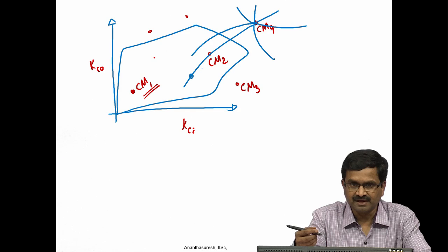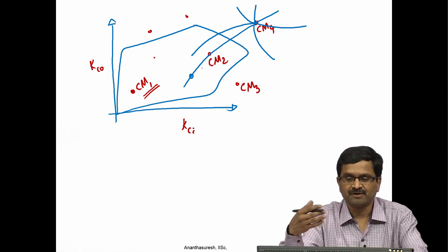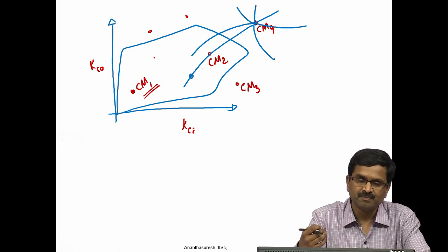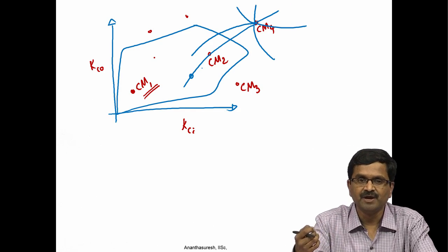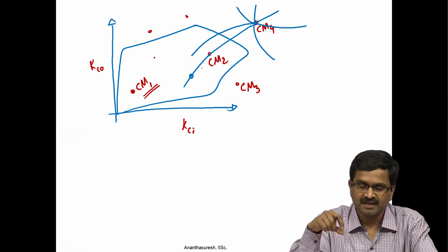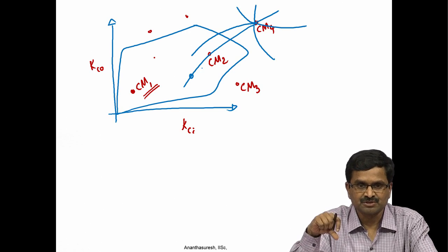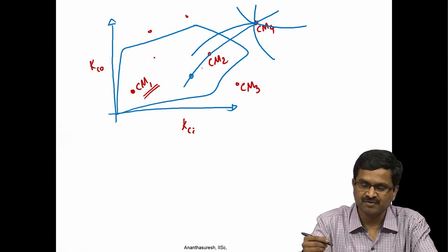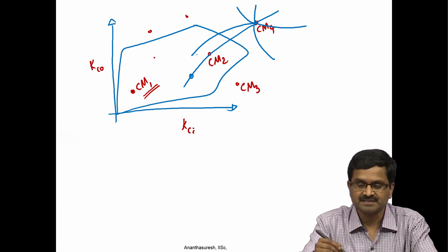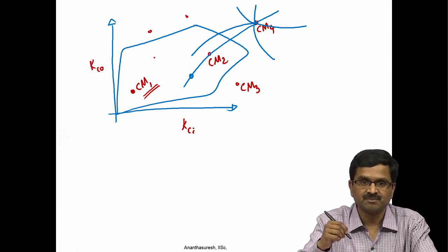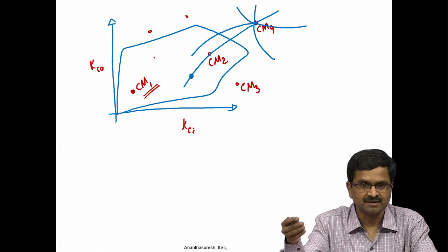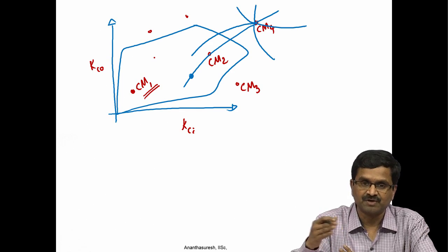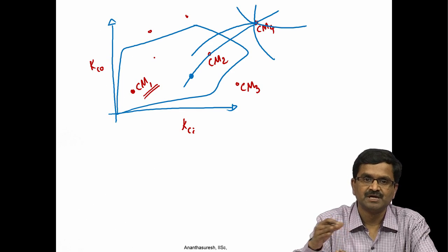While designing that, we can look at the strength as well as manufacturing considerations such as the minimum width of the beam that can be made using a process that you can select. You can select manufacturing processes and then set the manufacturing process specifically in terms of size, thickness, narrowest beam, widest beam and smallest hole. All that can be specified, and accordingly we can redesign and get something that comes inside the feasible space and satisfies all other requirements: manufacturing, strength, and of course functional ones like stiffness, displacement and force.